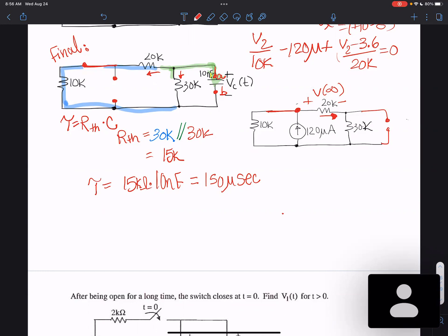You're going to see my favorite way is always the same. Combine the two into series. Correct. Or a voltage divider again. So if you combine the 10K and the 50K in parallel, then you could find the current going through both of them and do I times R and get the voltage. I'll call that V3. And then do a voltage divider there.